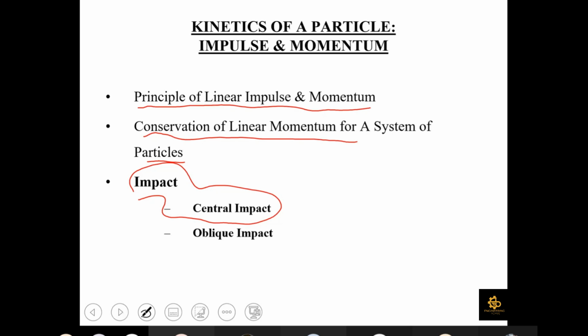and therefore they should not be included in our impulse and momentum analysis. Moreover, there are going to be some forces which are producing a very small amount of impulse, such as the weight or the force of an elastic spring. So they should also be neglected while considering the impulse and momentum analysis. In contrast, you need to consider only impulsive forces, that is, forces which create a large amount of impulse, in your impulse and momentum analysis.